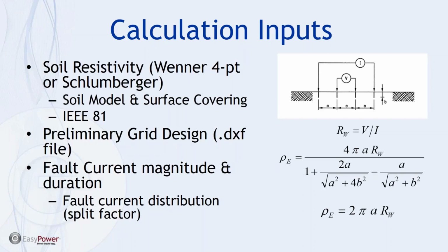The other important input, obviously, is the grid design. You generally start with a preliminary grid design. You can make it with any sort of CAD or FreeCAD program. You can generally import DXF files, and that's a good way to start, and then you iterate to get to your safe design once you've got all of your inputs in.